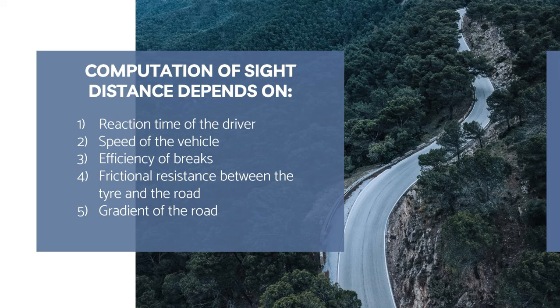Reaction time of the driver is the time taken from the instant the object is visible to the driver to the instant when the brakes are applied. The total reaction time may be split up into 4 components. In practice, all these times are usually combined into total perception reaction time suitable for design purposes, as well as for easy measurement. Many studies show that drivers require about 1.5 to 2 seconds under normal conditions. However, taking into consideration the variability of driver characteristics, a higher value is normally used in design.